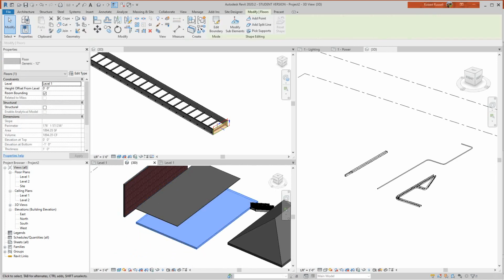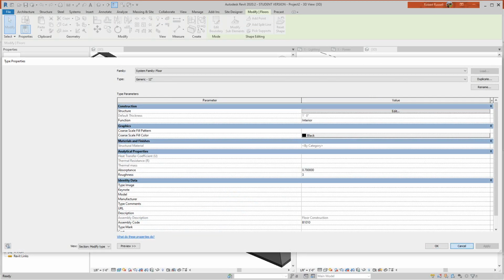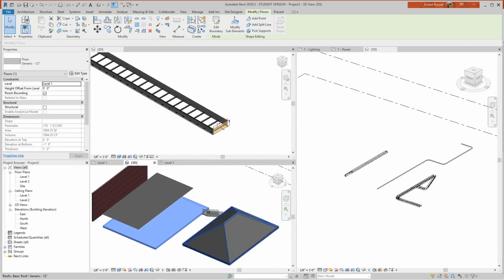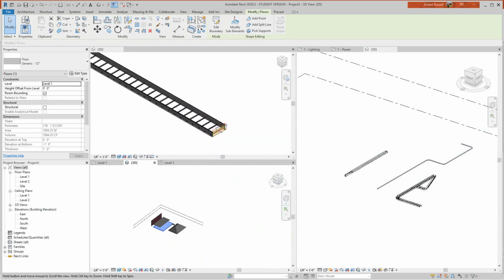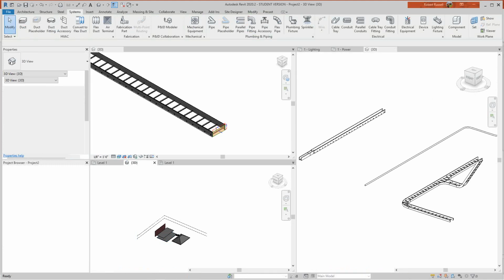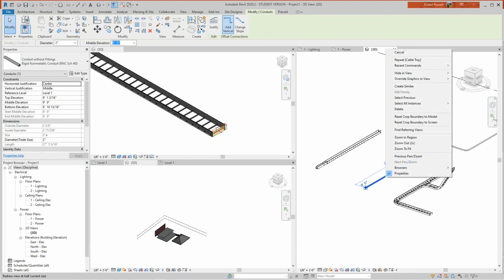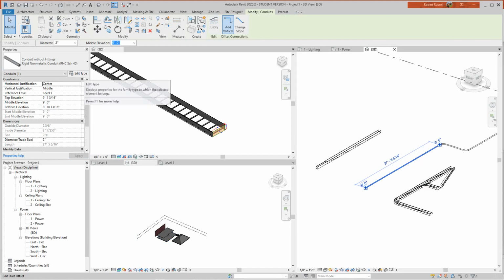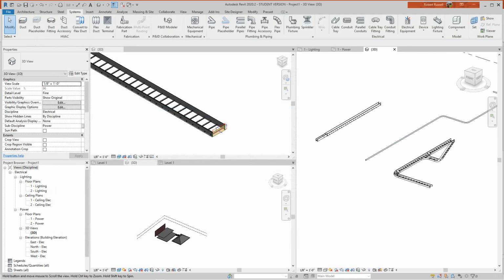And the same thing happens with the floors. We go ahead and edit the type, and we build the floor out the same way. So that's basically what's happening with the system families. The roofs, the floors, the doors, and all these other things here. And now on this end, the same thing. We just go here, and for a system family, we select it. We'll go into type properties, and we'll edit type, and then we'll duplicate it. And then we'll go and modify and manipulate things. But as far as making these system families, we can't really make them.